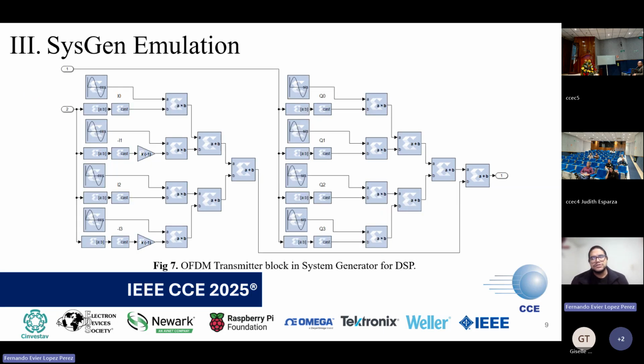After that, we take those components and go into the transmitters. We have 2 transmitters. This is the block diagram for one of them, specifically antenna 0. In this case, we multiply by each of the oscillators, and we apply the Alamouti sequence using negation with an amplifier with a value of -1. Later on, we add up all the signals into a single one.